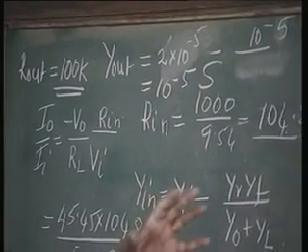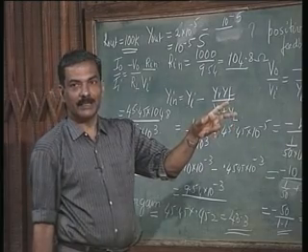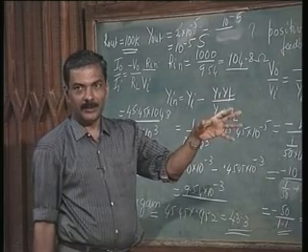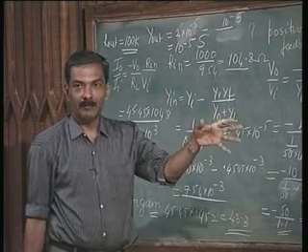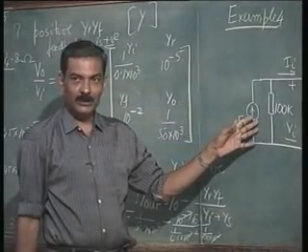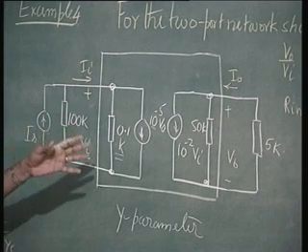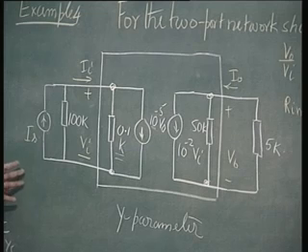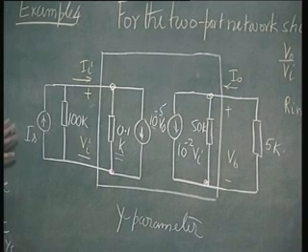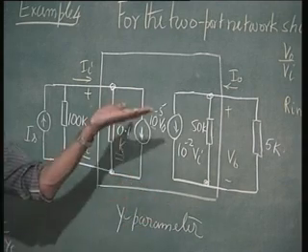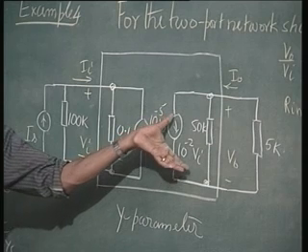The self admittance at the output is 1 over 50 K, or the output impedance, self impedance is 50 K, but now because of interaction, okay, from the input it has become 100 K, it has increased. That means again this same effect is there because of positive feedback. The impedance level both at the input and the output have gone up. From 50 K it has gone up to 100 K. That means there has been an effect of negative resistance on this side also.